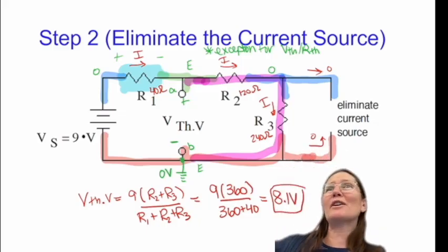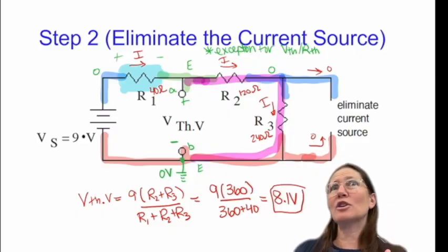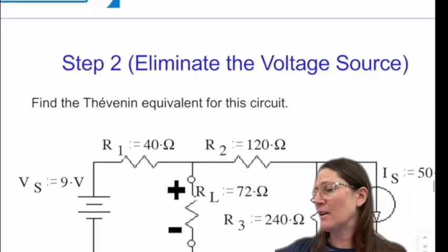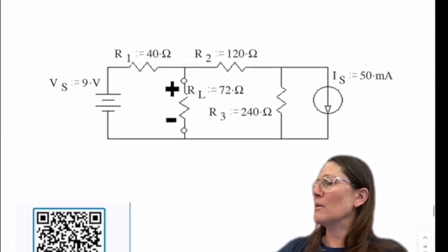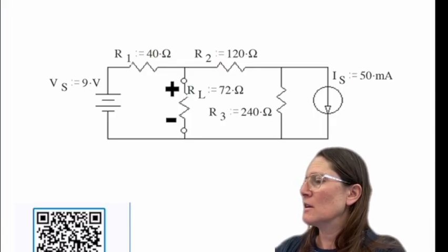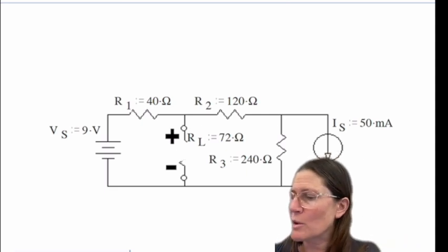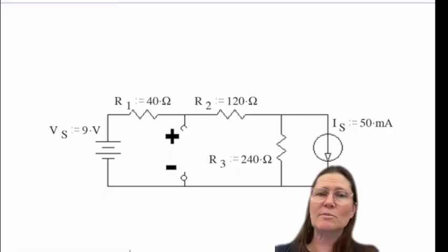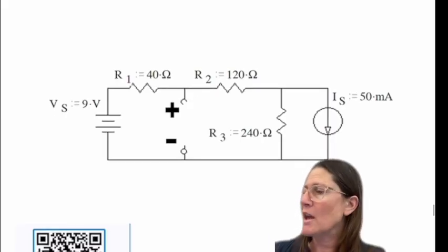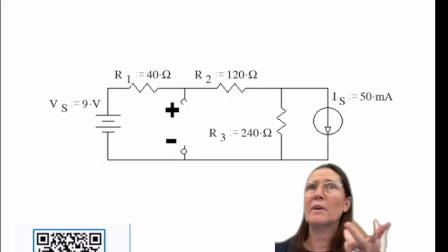Okay, so if I don't see these as voltage dividers or current dividers, or I don't want to use superposition, then you could go back to our other techniques. I would still find RTH the same way, so that's not going to change. What's going to change is I'm just going to leave the elements in there, and this time I'm going to use KVL, KCL, and Ohm's law.